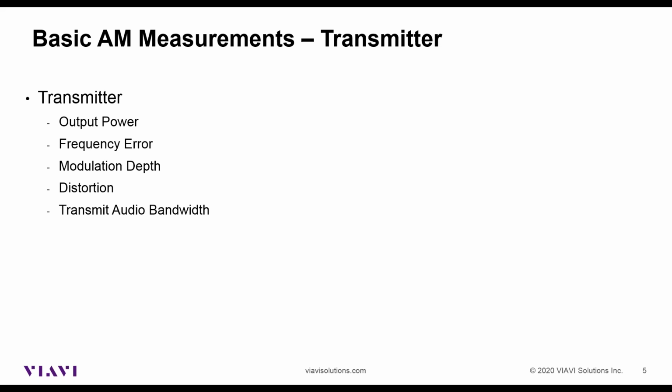Another thing we might want to do, and this is more often tested, I would say, on analog radios than maybe FM or digital, is actually look at the audio bandwidth as well, especially for those ground-to-air radios. It's a test that typically is done by many of the users.